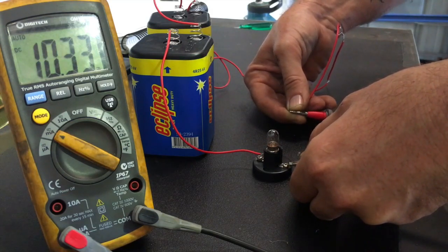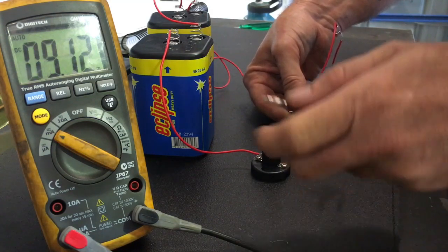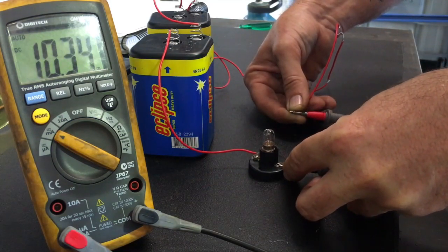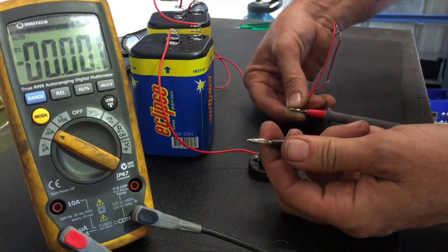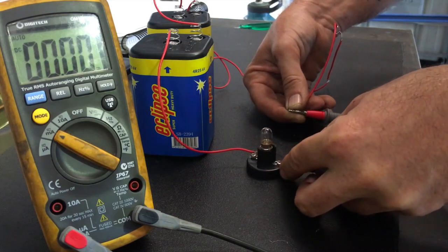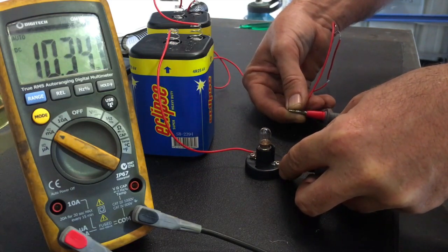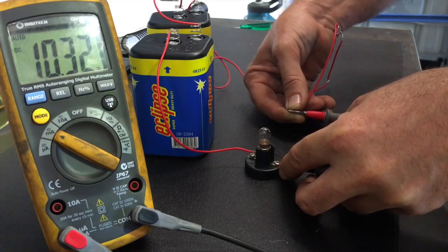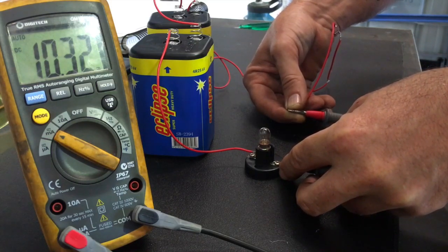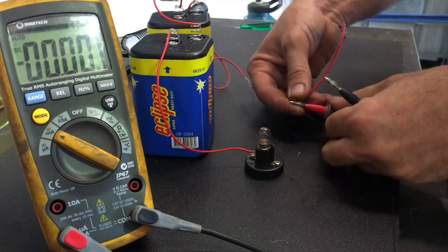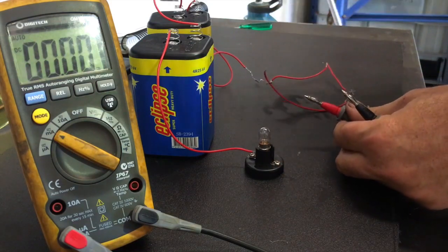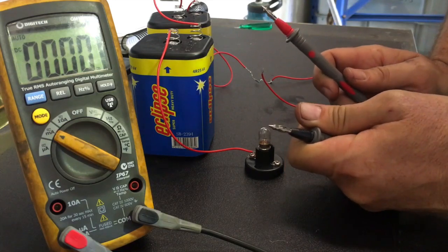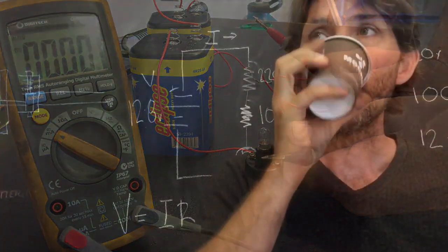But be careful, because, for example, this circuit is fused at 400 milliamps. If this was working correctly, I would straight away blow the fuse in this multimeter because an amp would be flowing through it. So just be careful when you're measuring current, because at that point it's in series, there is no secondary path. The entire current does pass through your tester. Just something to be aware of if you decide to go the route of testing current flow.